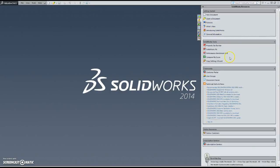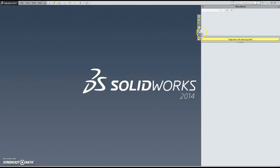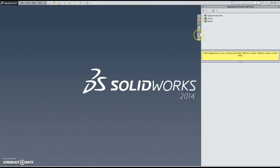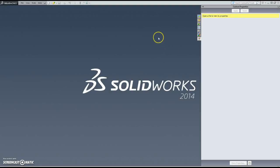You also have your Resources tab, which has your tutorials, your What's New, along with some other properties. Your Design Library is next, where you can import commonly used items. You've got your Toolbox and 3D Content Central, etc. File Explorer, we can look through the files that are on your system. This menu is for drawings, that's why it's not populating anything right now. And then you've got your appearances and scenes, and then custom properties, which I haven't filled out on here.